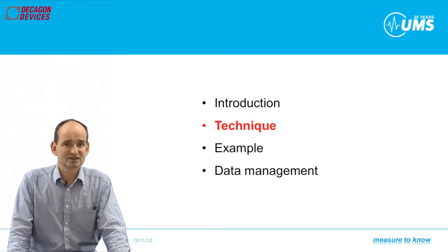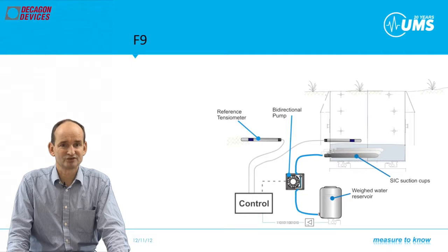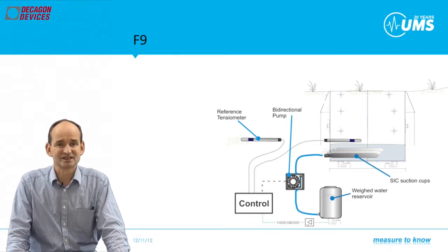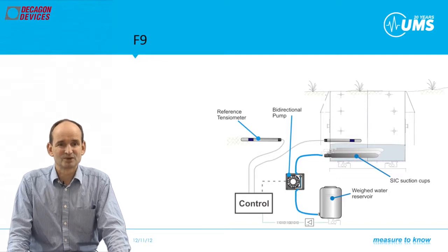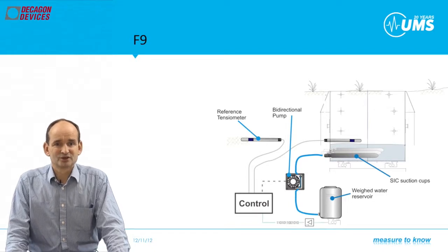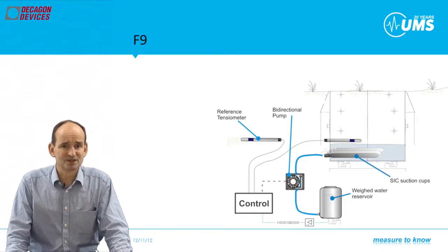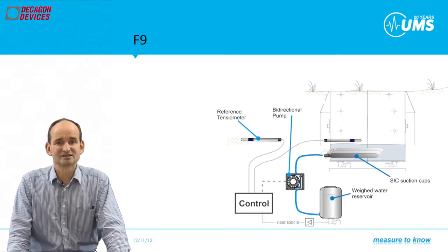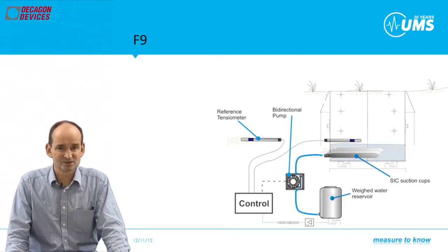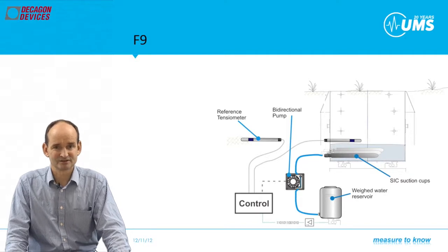This schematic view shows the technical components of a lysimeter with a cross-section of 1 square meter. In Smart Field Lysimeters, it looks pretty much the same, but we measure the lysimeter matrix potential with a virtual tensiometer, as we take the pressure level directly in one of the 3 suction cups at the lysimeter bottom. The controller program takes into account the flux parameters and responses and the response speed of the field lysimeter. Important to say that the field lysimeter must be filled properly. If this is not the case, the controller activates a default mode which keeps the lysimeter weight on the latest level.